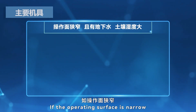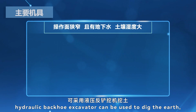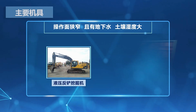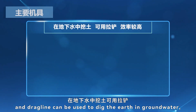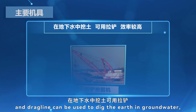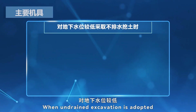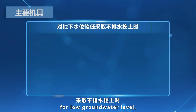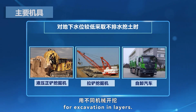If the operating surface is narrow and the soil moisture of groundwater is high, hydraulic backhoe excavator can be used to dig the earth. Dump truck can move the earth, and dragline can be used to dig the earth in groundwater, which is efficient. When undrained excavation is adopted for low groundwater level, different machinery can also be used for excavation in layers.